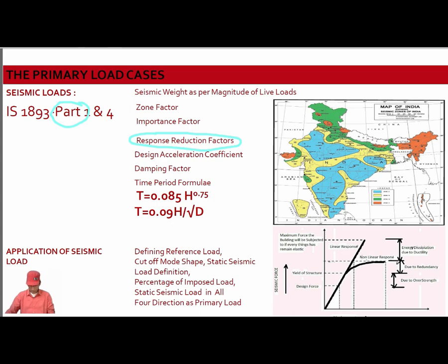This explains why we reduce. There will be some overstrength in the structure, then there will be some strength. The structure will have capacity for energy dissipation due to its ductility, because a structure doesn't fail until lots of hinges are created within the structure to create instability.